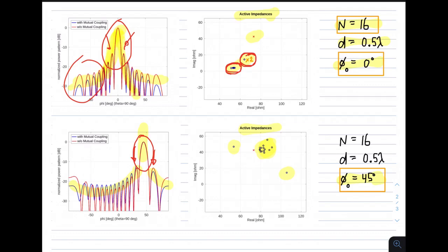And really the best you could do in terms of impedance matching this thing is trying to choose a source impedance which is somewhere in this ballpark. And you can see once again that finding a single source impedance that gives you a good match to all the elements is quite challenging. So what's commonly done when these arrays are actually designed is to try to figure out alternative geometries and choices of materials that cause all these things to get closer to some value. Not necessarily to the self-impedance, but just clustered in such a way so that even accounting for scan dependence, you get a sufficiently good match.